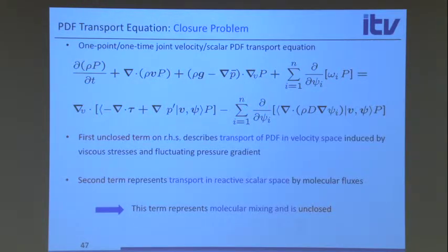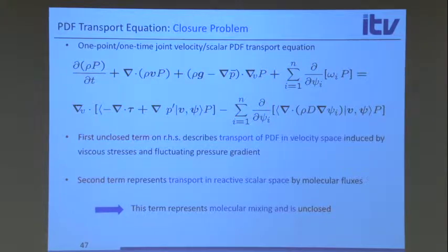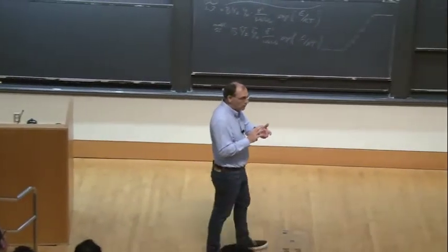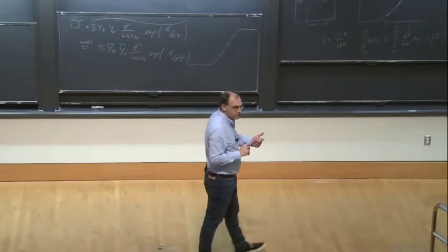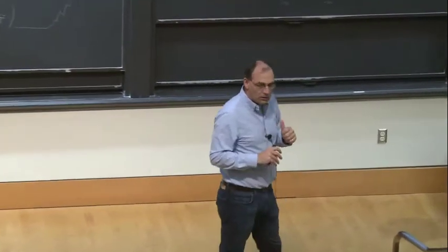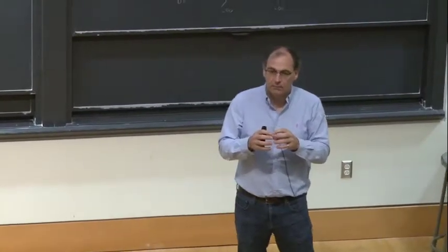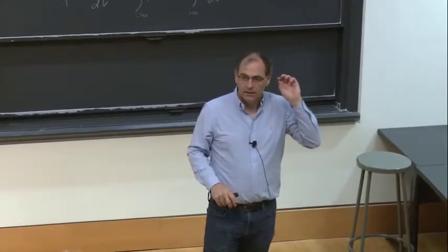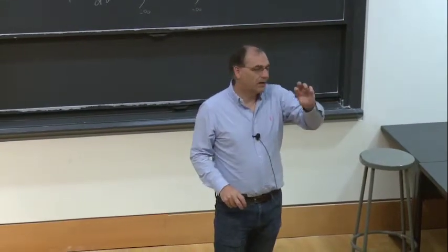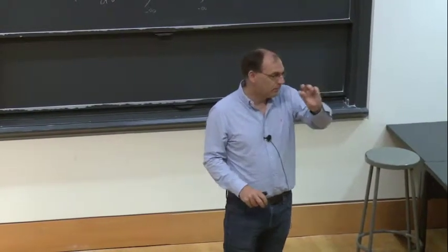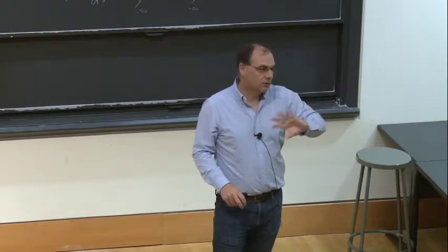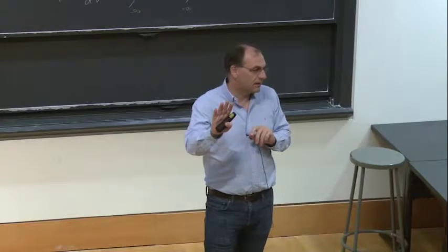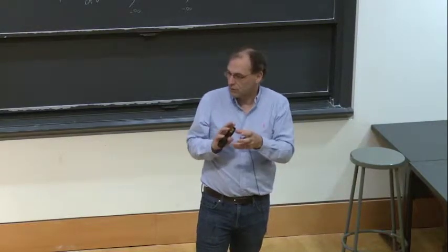So one other thing that is very important is that if you have two terms, here in flames, we said you have molecular mixing somehow, and then the chemistry comes afterwards. And we saw earlier that if I just evaluate the chemical source term, and from this I evaluate a chemical timescale naively, we did this before, then we got a certain value for that timescale, and then we evaluated the timescale by considering the flame structure.